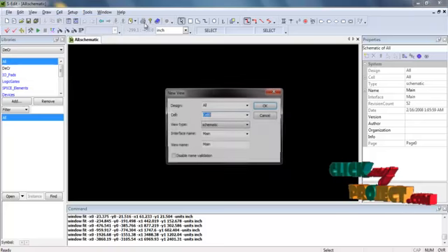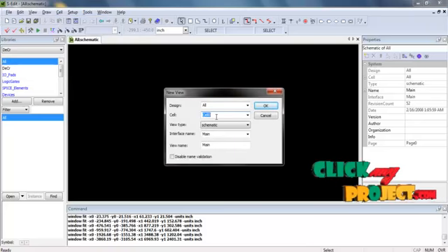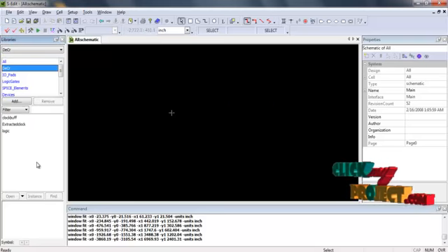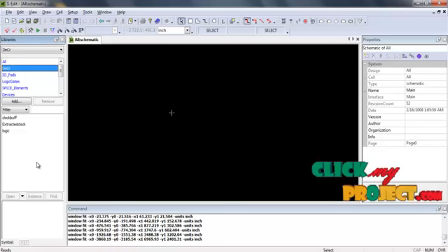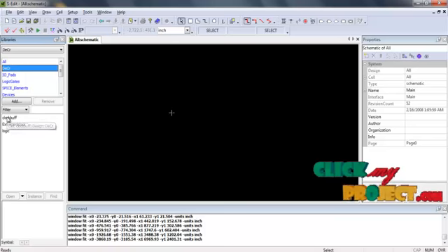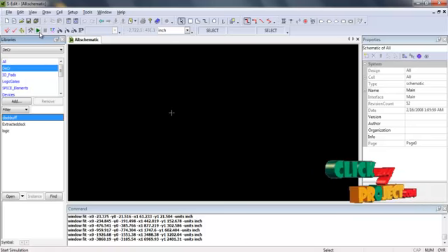Cell, New View, to create a new cell with the desired name. Our product can be implemented using three different cells. They are named clock buffer, extracted clock, and logic circuit unit. First we are going to simulate the clock buffer unit. Select the clock buffer and start simulation.